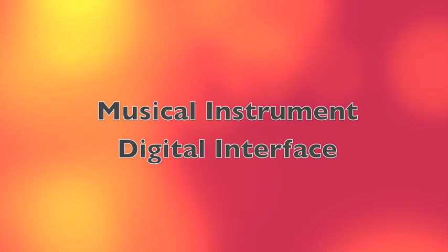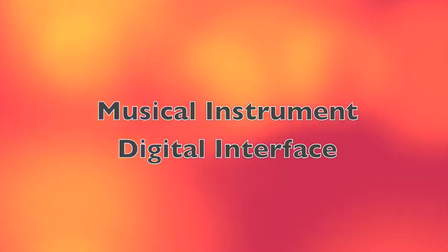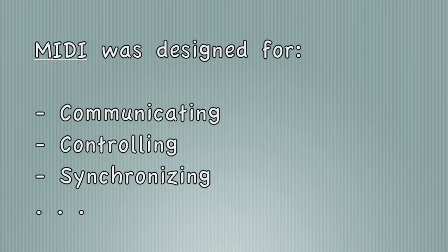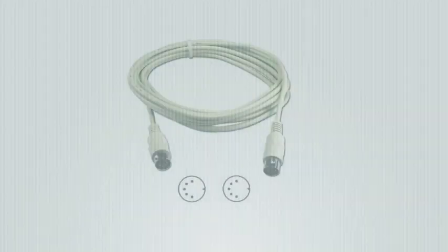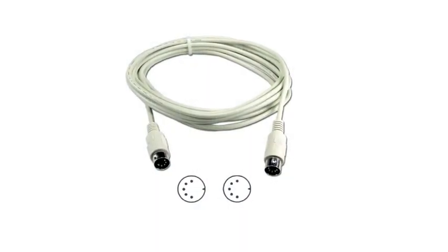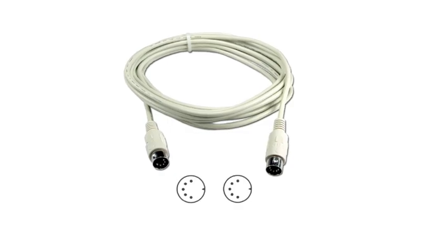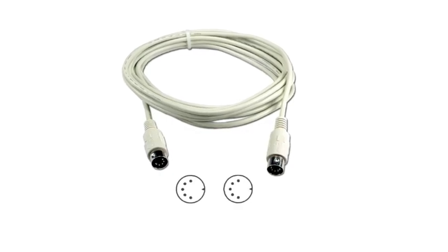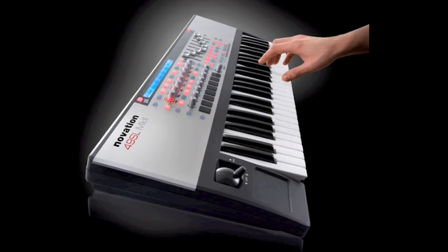What is very important to understand right from the beginning is that MIDI does not carry audio. MIDI stands for Musical Instrument Digital Interface. MIDI was designed for communicating, controlling, and synchronizing equipment such as electronic musical instruments and computers. MIDI was originally carried using DIN connectors, but is now also carried through USB cables.